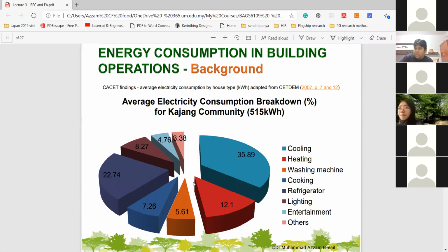We can concentrate on these, and for architects, we can concentrate a lot on cooling. We can also concentrate a lot on lighting as well. These are the two things that we can really make an effect on. So we can look into the lighting, the sizing of windows, the location of windows, shading them. We can look into the specification of our walls, in terms of the insulation, the thickness, the materiality, the U value of the walls.